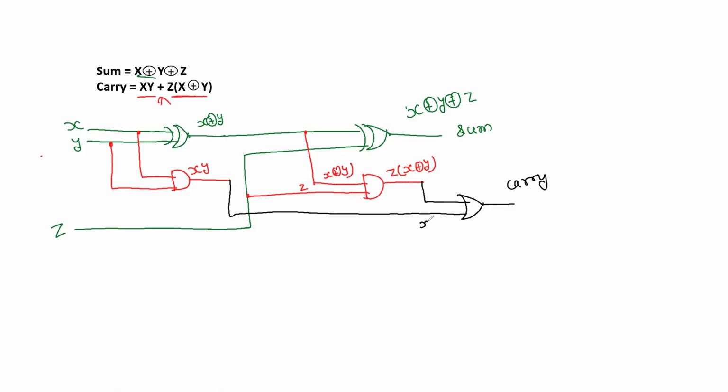So this input is here XY. Finally, the carry expression is XY + Z(X XOR Y). Like this, we are able to implement it here.